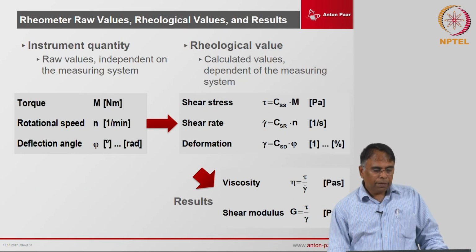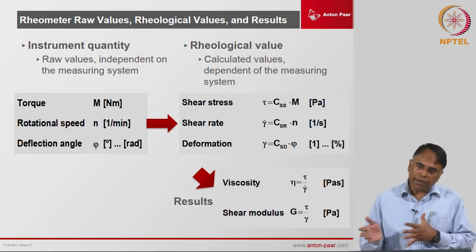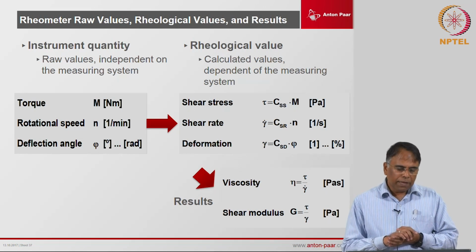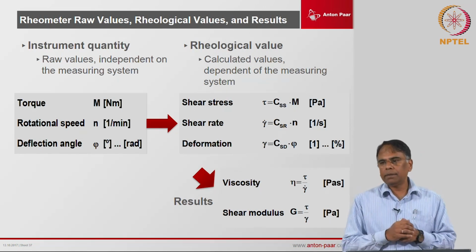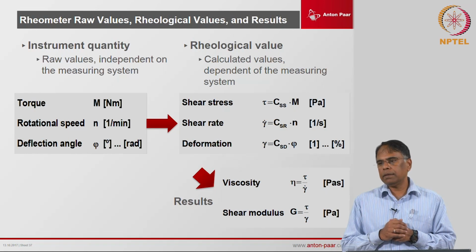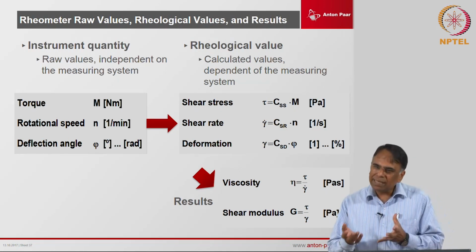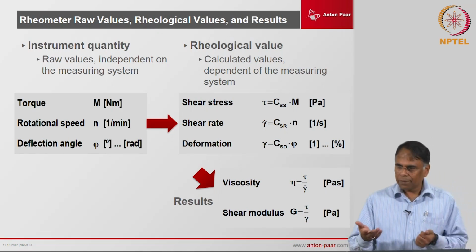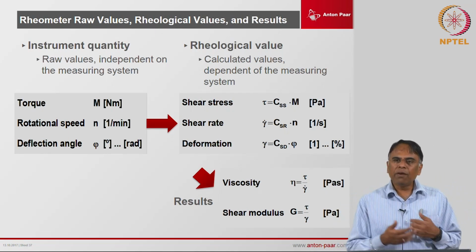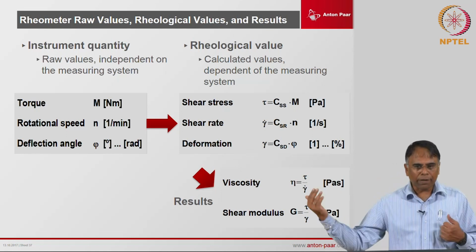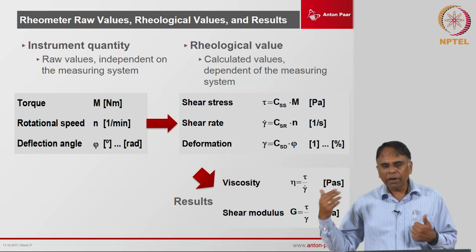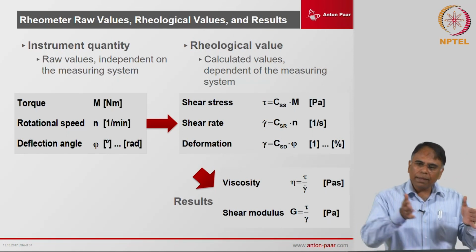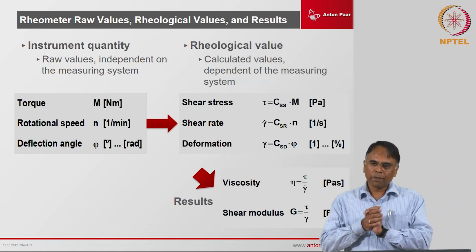Detecting the problem. When we are measuring these tests, we are going to apply certain parameters. The basic thing that we are applying in all the tests is strain, measuring the stress. And we have to see if there is noisy data, for example. So, we have to understand whether you are measuring on a rheometer in the range of that rheometer. That is the first thing.